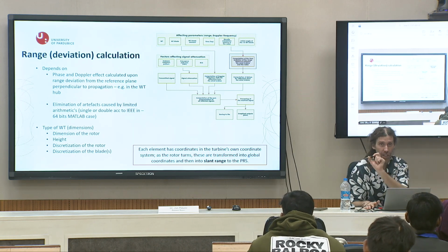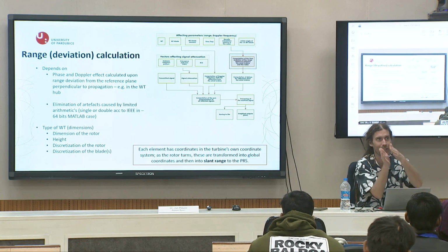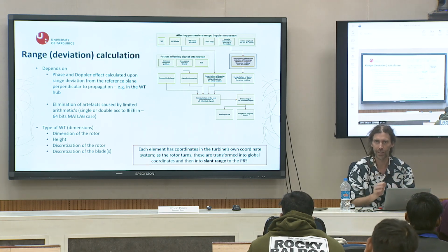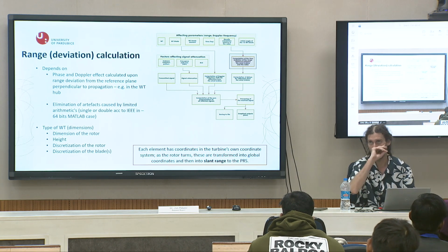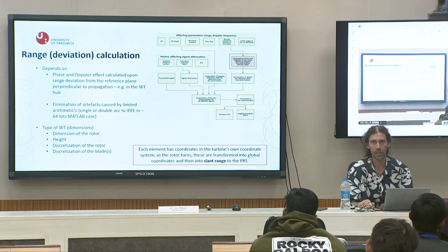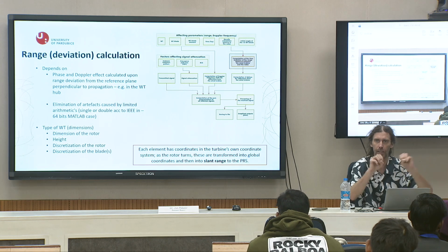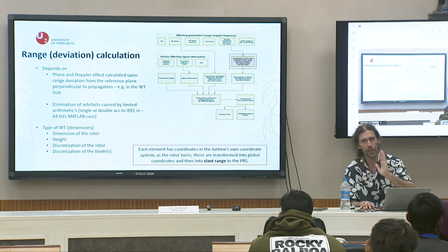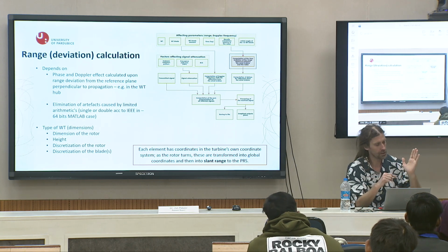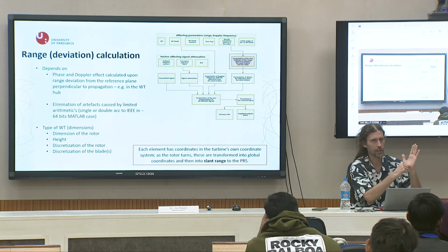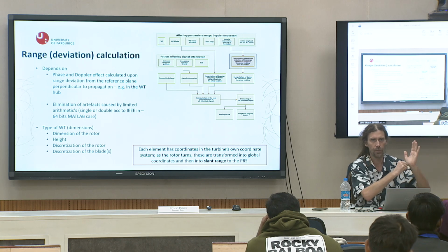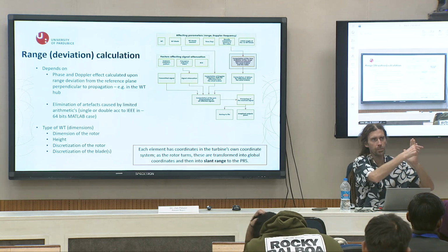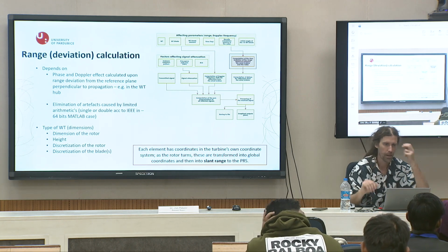I know that the change will be small because it is just elements one by one, but still it will cause, as we saw already in the simulation result, this spreading in spectra, because each element has different speed. Elements that are close to the nacelle have very, very low speed. The end of the tip, very, very high speed. It is Doppler, generally.